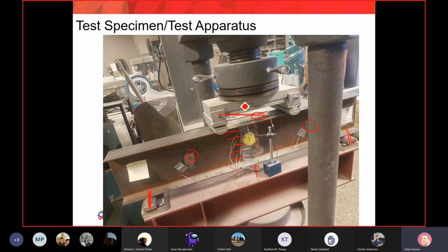Okay. Now also look at how the beam is loaded. The machine will push here, so that's the load coming from the machine. And we have kind of a bridge. What this bridge does, you can see it splits your load into half and half. Okay, do you see that? I need confirmation. This bridge here splits the machine load into 2 halves. Like if I apply here P, then P over 2 will go here, and also P over 2 will go to the other side. I need some confirmation. Yep.